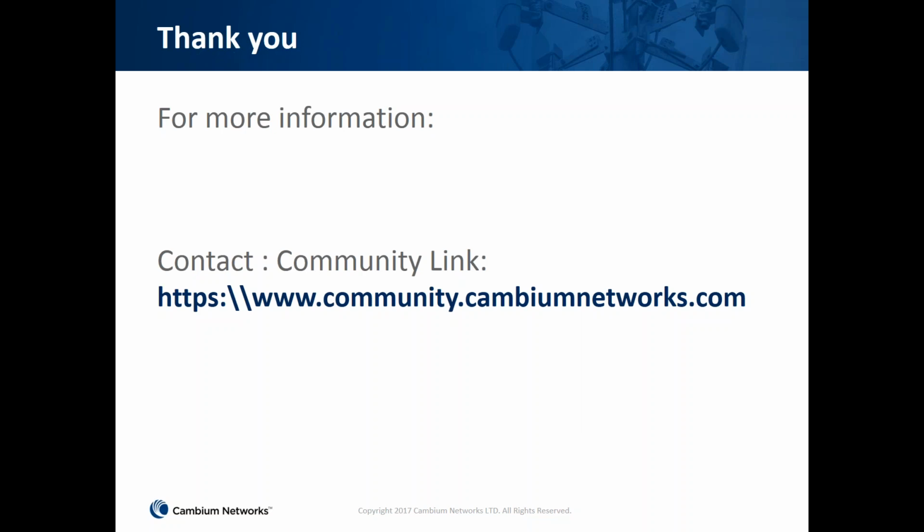The Cambium sync is a new method which we can use for synchronization of multiple radios together with an injector and power supply, which is the CMM5. The CMM5 allows you to power up to 4 units and synchronize them all at the same time. So instead of having at the bottom of the mast 4 power supplies and 4 PTP sync injectors interconnected, you now have only one CMM5 which will provide the power and synchronization to all 4 units. Right.